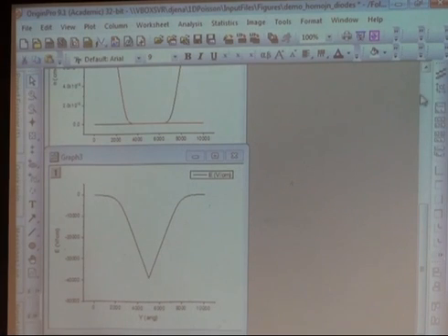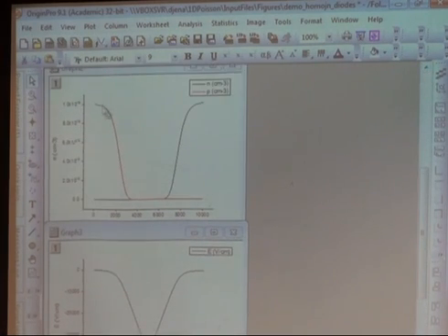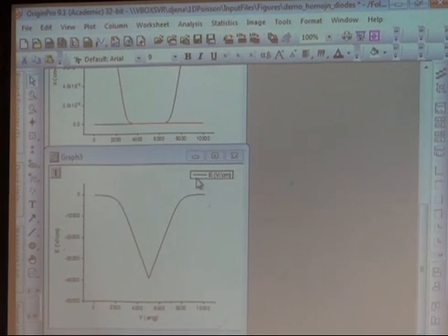Look at the carrier densities. Holes on the top, P side, depletion region, and no holes in the bottom, minority carrier. If you plot in the log scale, you will see the minority carrier density has done it correctly. Electrons at the bottom, N-type, then depletion, and then minority carriers on the top. Electric field, I think we have done that many times. It looks triangular like we have done before, but there's a little bit of broadening at the edges. This is because of the Debye length. The depletion edge is not very abrupt, and we neglect that in a normal analysis, but it shows here.